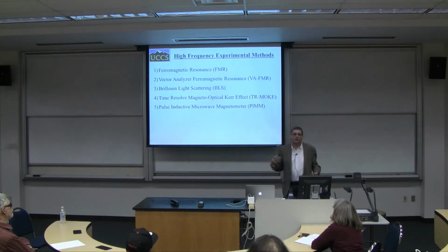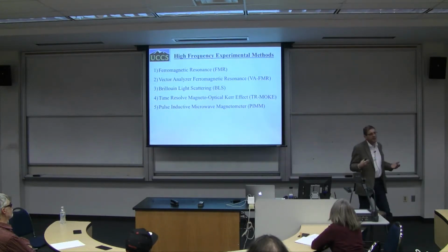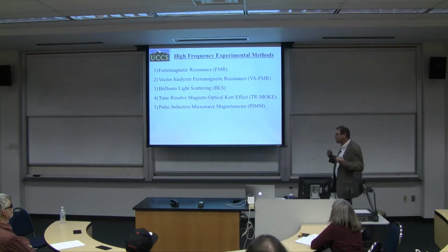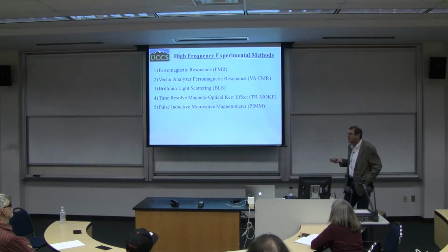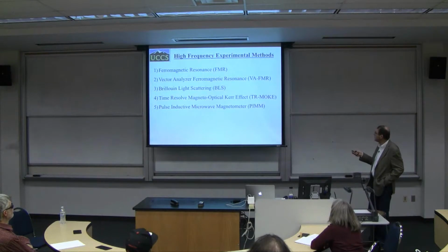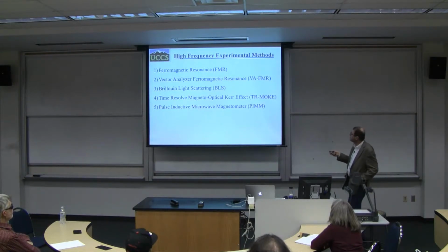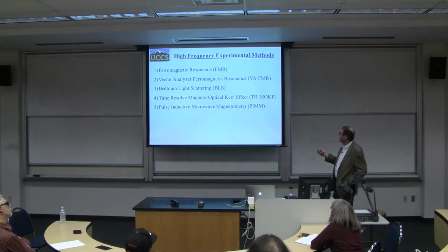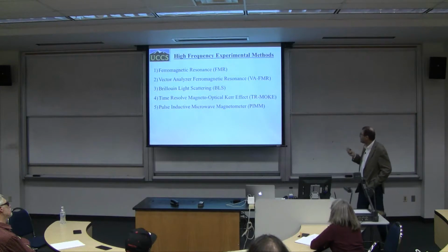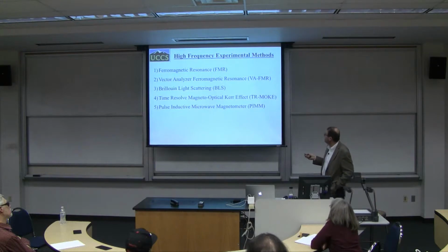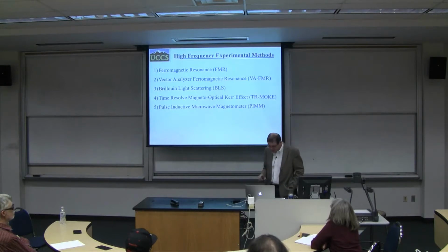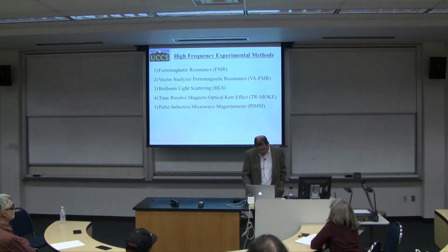Now, everything I have told you so far was about static measurements. So now what we would like to do is see how these materials behave at high frequency. In order to do this, you have to use a series of techniques. One of them is ferromagnetic resonance, and I'm going to talk a little bit about it. We are also using a vector analyzer FMR. We have Brillouin light scattering in our lab, but none of the data which I'm going to show you today were done with BLS. And there are other techniques like time resolved MOKE, which we also have. Pulse inductive microwave magnetometer is the system which I was helping build at NIST a couple of years ago, 10 years ago actually.